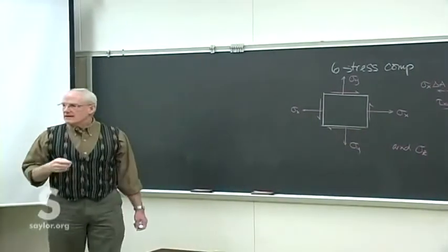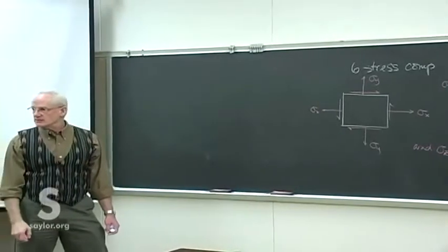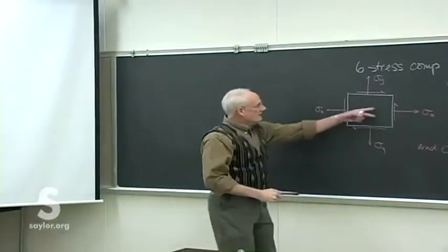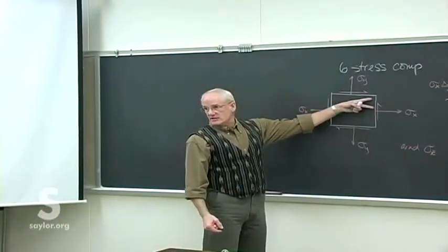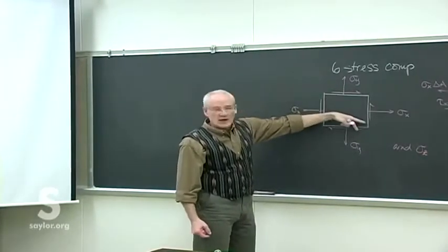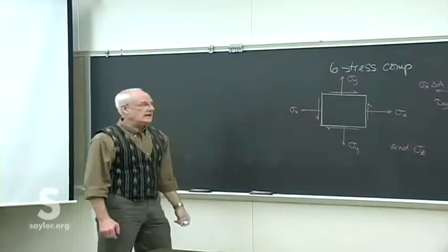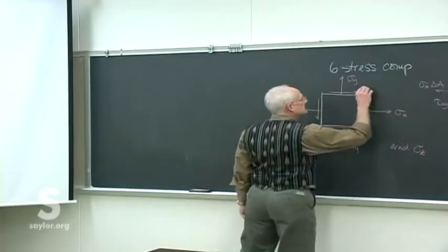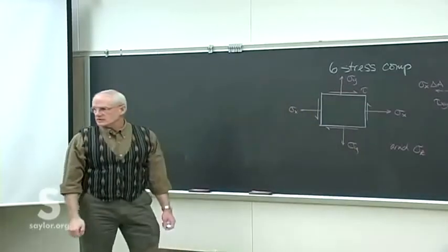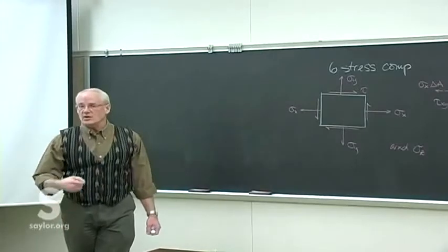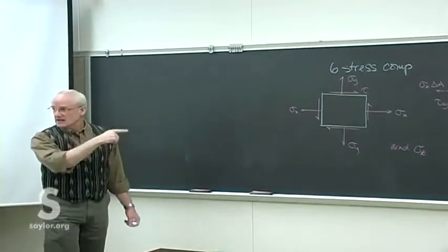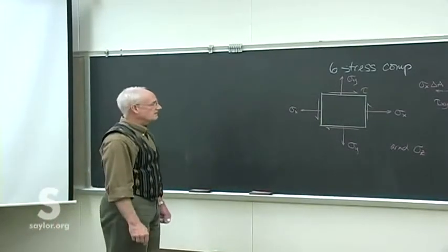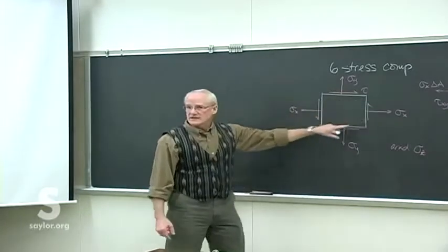shear stresses that must be drawn in that relationship to each other, or we don't have a force balance. Two on adjacent sides must either point towards each other or point away from each other, depending on which corner you're looking at. And it's not even important anymore what I designate them. I'll just call them the shear stress tau, because they're the same on all of the faces, because I can do this in any direction. I can do this all the way around the cube. All of the shear stresses must be the same, and they must orient themselves in this way.